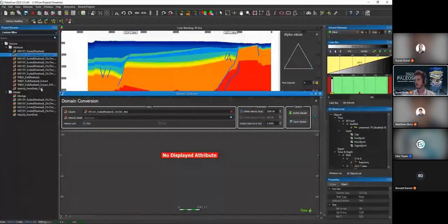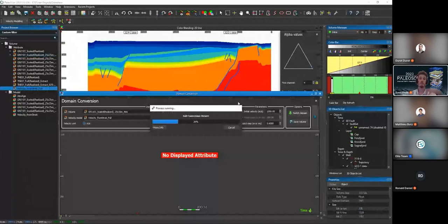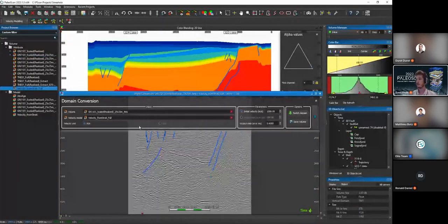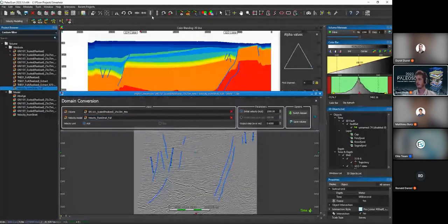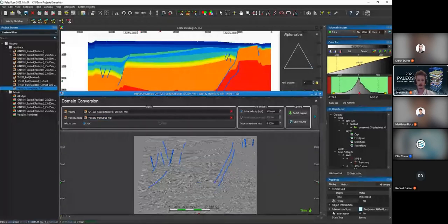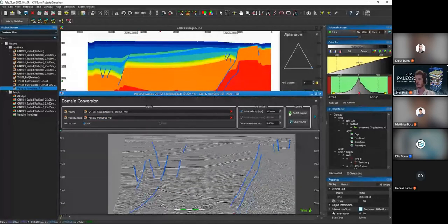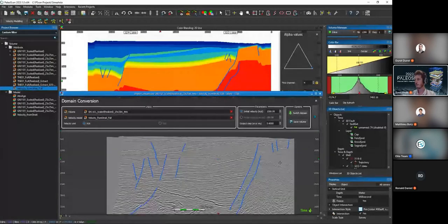Okay, so I'm just going to perform this just in front of your eyes. So right now I'm inputting a seismic volume, which is initially in time, associated to the velocity volume you see on top. Okay, I can adjust a bit the size of the data, the type of display, and then dynamically I can switch the data from time to depth and back and forth.